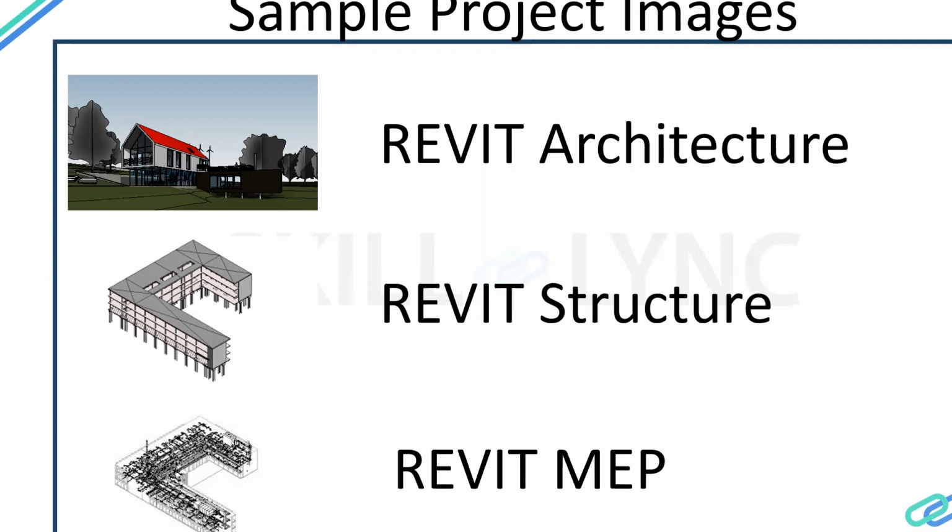I just pass the template to my team. For example, the line thickness should be 2 mm, the text should be Times New Roman, or the ducting placed for supply should be in blue color. Those are the standards which I prepared in my template.